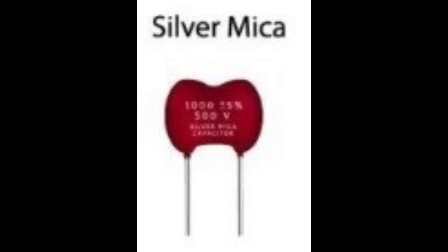Silver mica capacitors are used in applications which call for low capacitance values and high stability, while exhibiting low losses. Their main use is in power RF circuits where stability is of utmost importance. Silver mica capacitors are used in high-frequency tuned circuits, such as filters and oscillators.